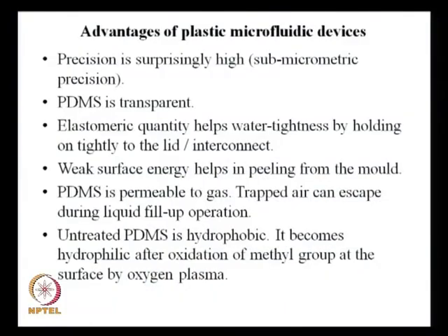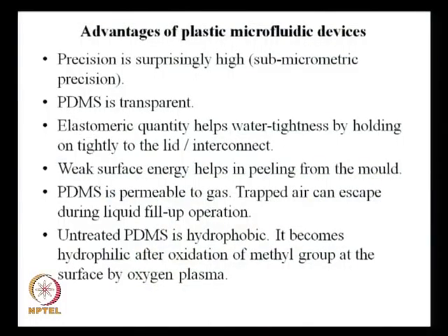Now, with PDMS, what I learned is that PDMS is permeable to gas, so if there is any trapped air inside the channel when you fill the channel with a liquid for the first time, this air can permeate out of this PDMS layer, and so the liquid fill up operation will have less hindrances.